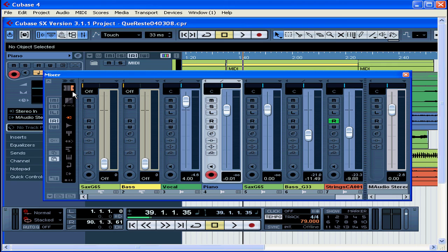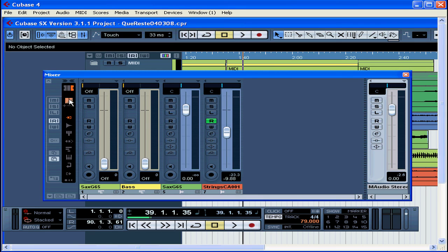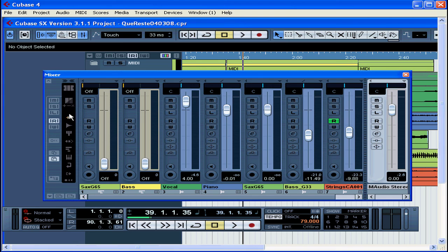These settings affect the Remove Can Hide from Target function. For example, if you exclude inputs, then inputs won't be hidden when you click Can Hide. That's this button here. Now my output channel is still here. These buttons hide from view all channels of the particular class represented by the icon.